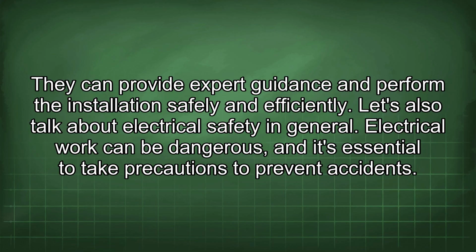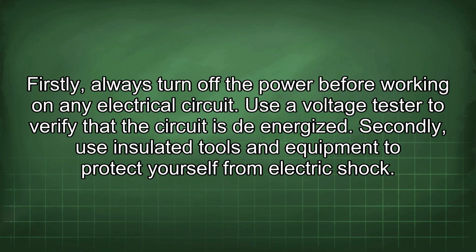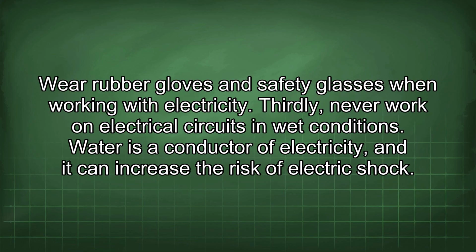Let's also talk about electrical safety in general. Electrical work can be dangerous, and it's essential to take precautions to prevent accidents. Firstly, always turn off the power before working on any electrical circuit. Use a voltage tester to verify that the circuit is de-energized. Secondly, use insulated tools and equipment to protect yourself from electric shock. Wear rubber gloves and safety glasses when working with electricity.